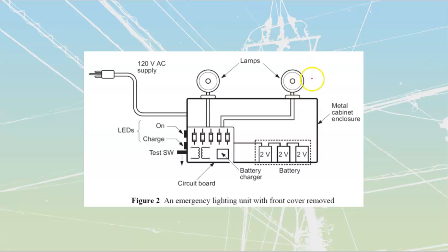So the number of lamps that you connect to these, particularly when you start having remote lamps, daisy chaining out a bunch of lamps over here, if you start connecting too many lamps, you run into the issue where you draw down that battery too fast. You're not going to be able to hit that minimum on time. So always make sure that you're following the manufacturer specs of these things. Just because it works when you flip the switch doesn't mean it's still going to have battery capacity a half hour from that. Make sure you are only using listed and approved components. You're not allowed to just take any old 6 or 12 volt light connected onto one of these systems, because it has to be something that the manufacturer has recognized as part of their assemblies.